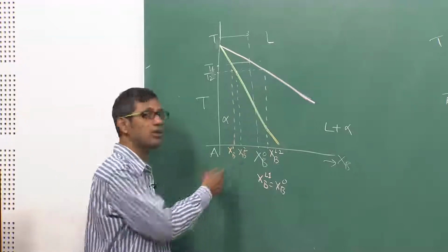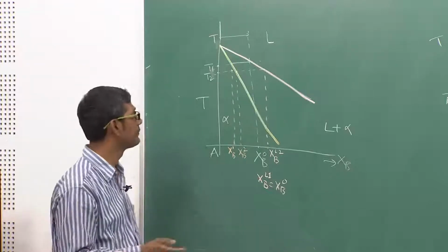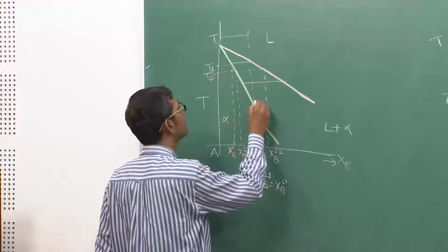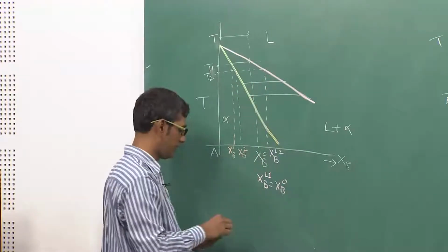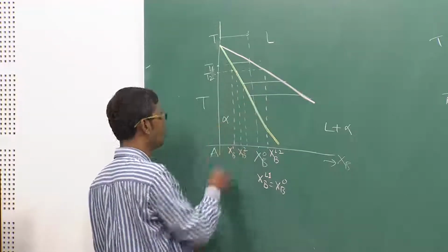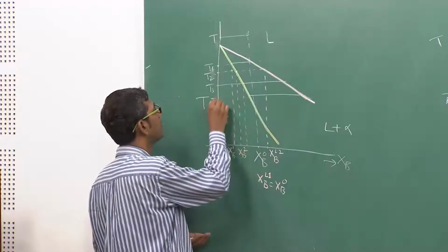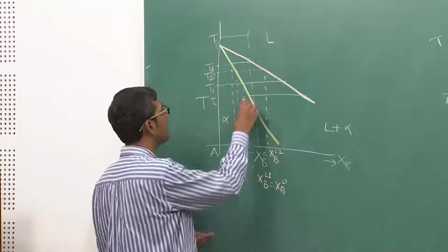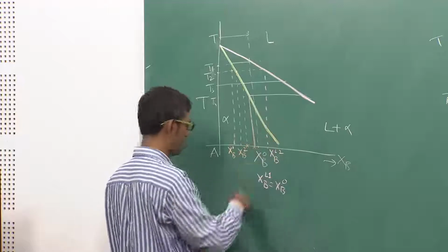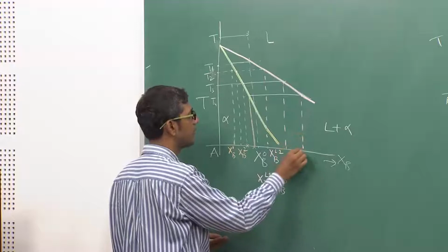The solid has a lower composition, so the remaining solute will be rejected into the liquid, and this will keep on happening as you lower the temperature further. At T3 or at T4, the solid which is formed has compositions given by these points, and the liquid in touch with the solid has a composition given by these points.